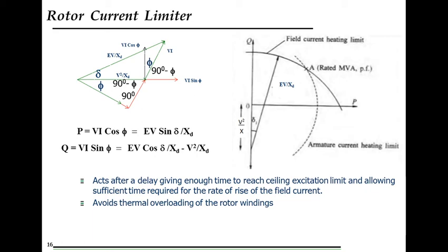So now we need to plot this on the PQ axis. Remember that while plotting this reactive power Q on the PQ axis, we will be plotting only on the positive active power side, that is the generation mode, which we had earlier discussed. Now if you remember the polar form of a circle, this represents a circle whose center is shifted by minus V square by XD.